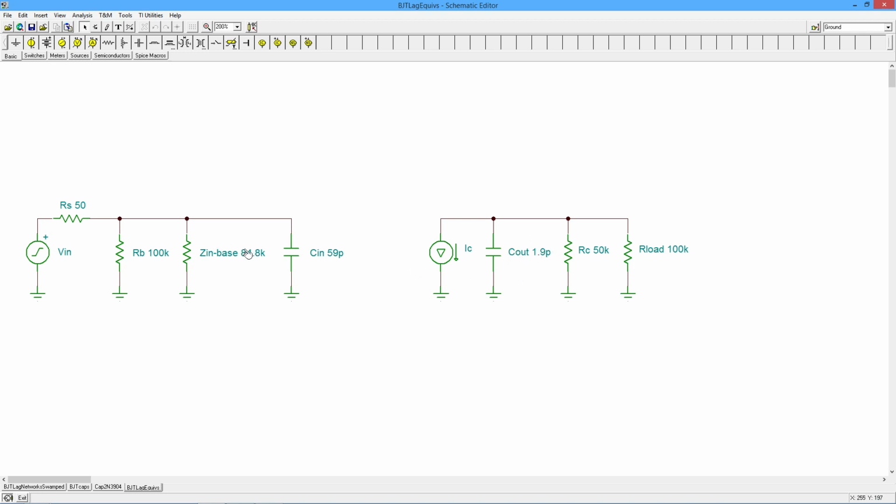So when we look at these two things, let's start with the output one first. You're just looking for that RC pair of values. 1 over 2 pi RC is the critical frequency. So you just want to find the Thevenin resistance associated with the capacitance. So here, these two things are just in parallel, and you're done. Back here, when you look back toward the source, to get the Thevenin equivalent, you're going to wind up putting these two in parallel with RS.